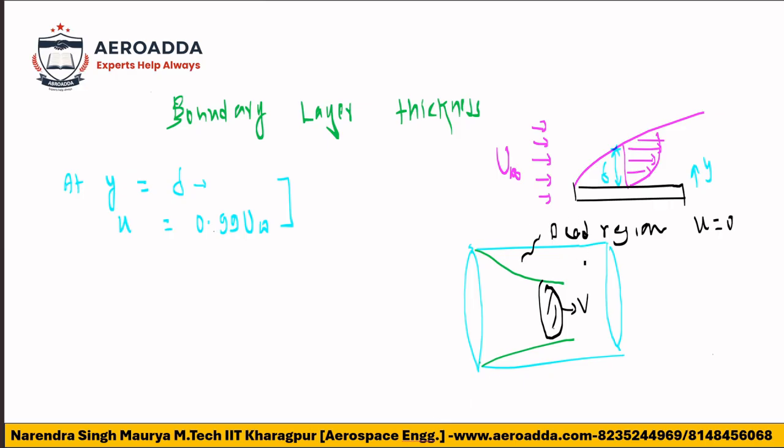Because of the formation of the boundary layer, as I have told you and might have discussed at another time, there will be losses. I had shown the work done factor in axial flow, where we multiplied by a constant of 0.98 to compensate for that parameter changing.